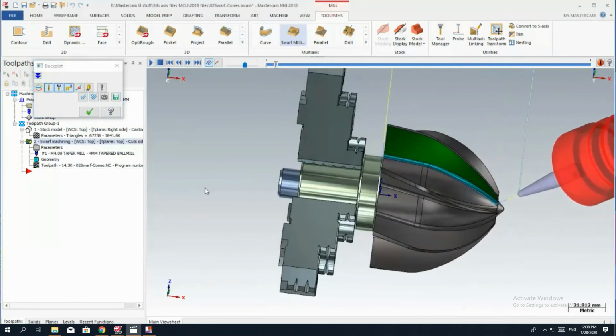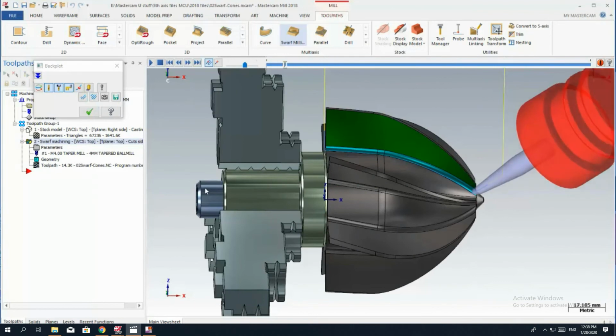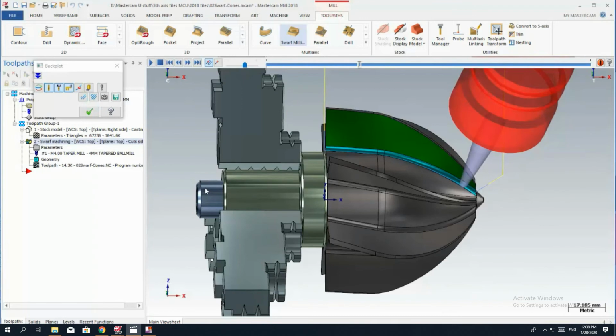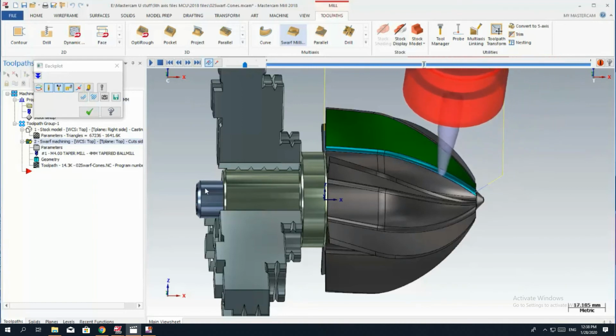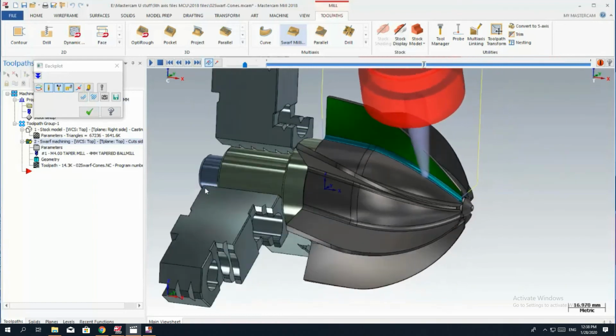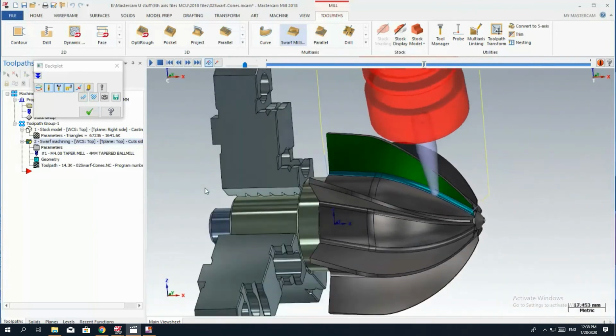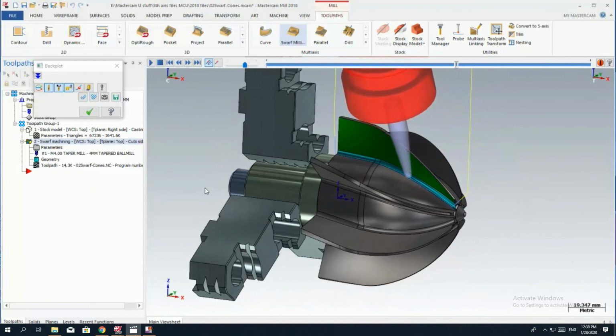You can see as the tool comes down, it tilts to the direction, comes right in. It's using the bottom rails, in this case these bottom surfaces, the fillets, to control the tip of the tool as it moves. And it's using the green face to control the side of the tool to cut along that face. So as you can see, as we stated, we're using the side of the tool to cut, and the tip is being controlled by our floor surfaces. Pull that tool right out.